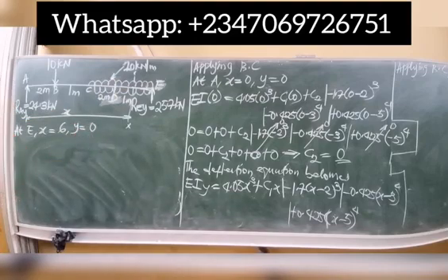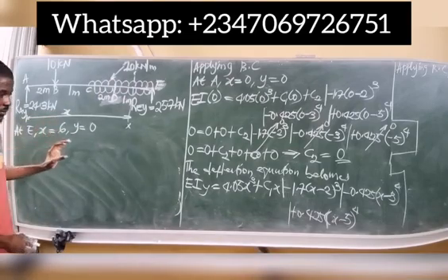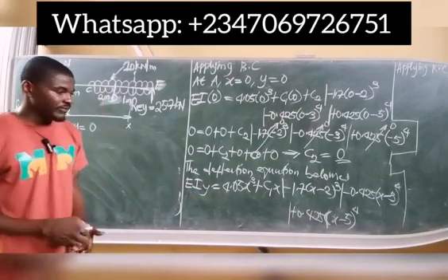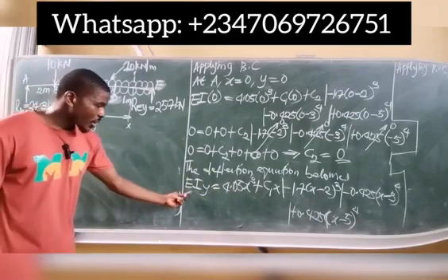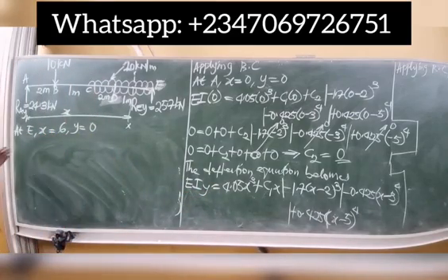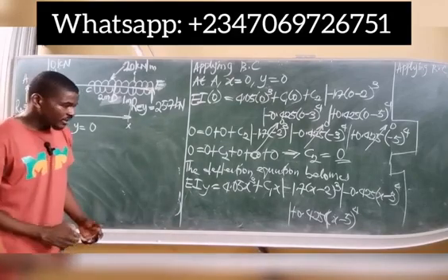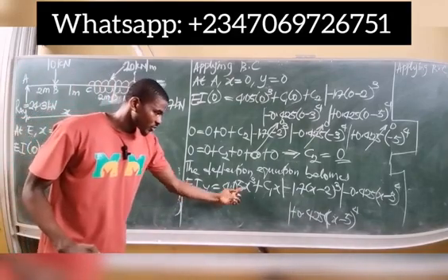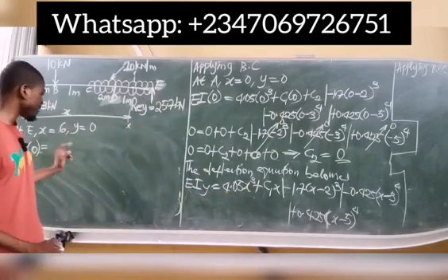There's no deflection there. So we simply substitute these conditions now into the obtained deflection equation. So here now we know the value of y still remains 0. So the equation simply becomes EI in place of y is 0, and that's equal to, next we have 4.05x cubed. Now x has a value and the value is 6.